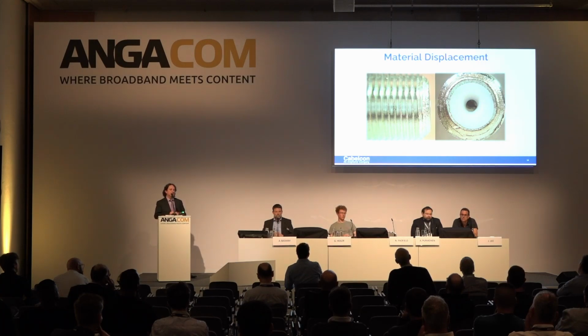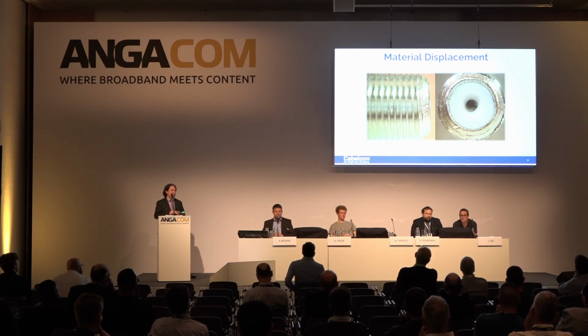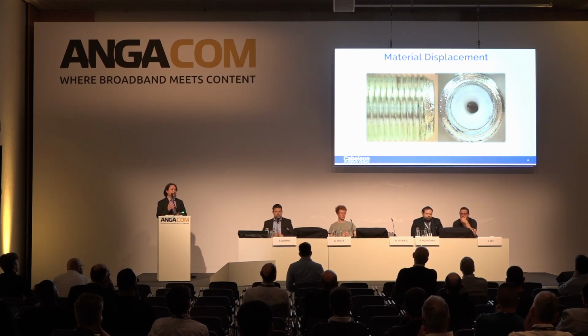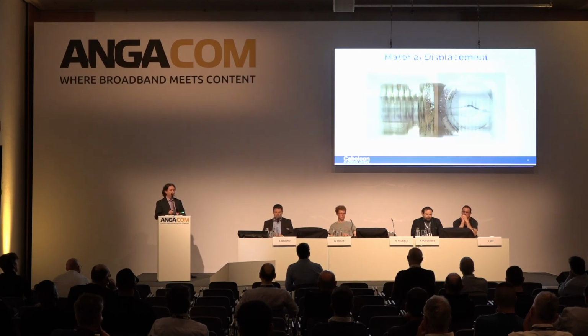One of the big pieces that we saw with the connector was material displacement. So here's a view of a port. On the left, we have a non-flat face. It's not 90 degrees to the threads. It's fairly central, but what we can do is put the conical interface on, and by the design of that cone on the front of the port that we're adding on, by torquing it up to 30, 40 inch-pounds and removing it, we're actually doing some material displacement in the port. The hard brass connector onto the less hard port means that there's that material displacement. So we can actually change the interface a little bit by adding the connector and the forces applied.